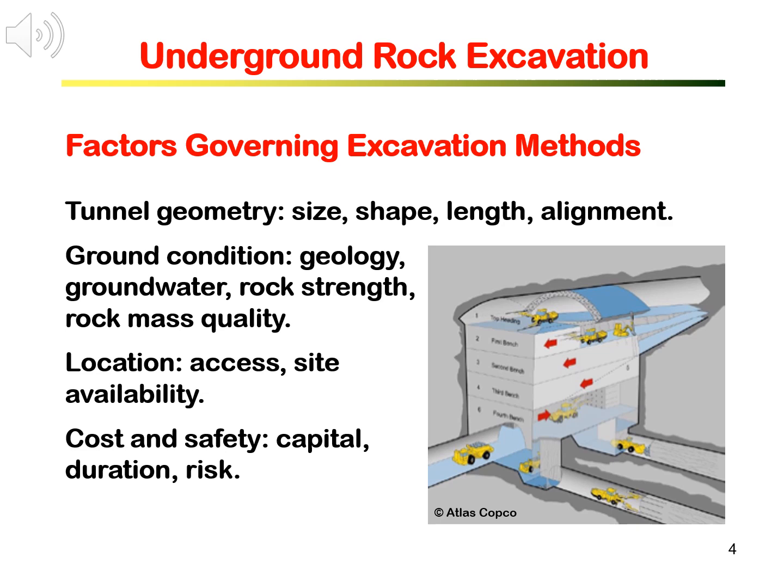Location is another factor to consider. Is it accessible, and is a suitable site available for TBM, particularly slurry TBM, which needs a very large area for a slurry separation plant? Other factors are cost, duration, and safety. For example, TBM is capital intensive, but has a rapid excavation rate.